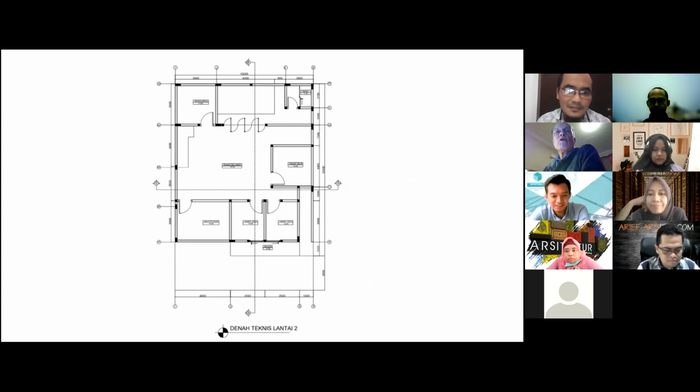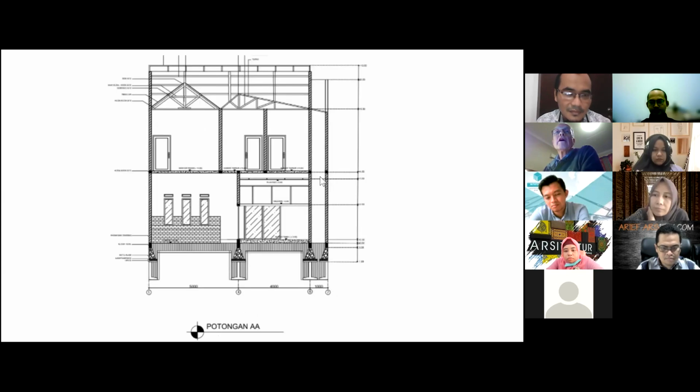And so we need a little tie beam to tie the wall back here into the floor diaphragm at each level. So here we need a little tie beam, and also up here there needs to be tie beams at this level, which is what I was discussing earlier.